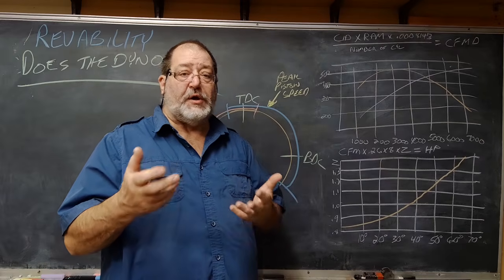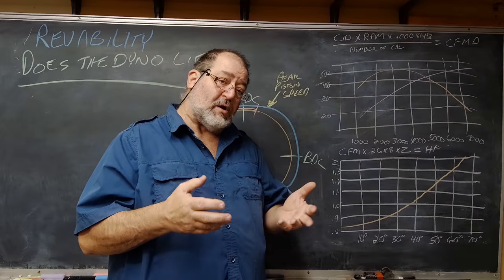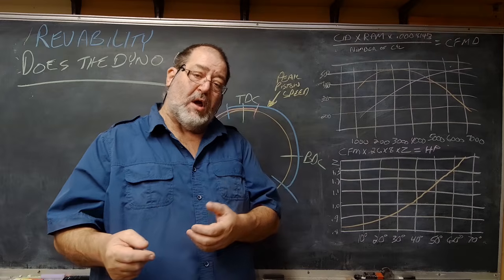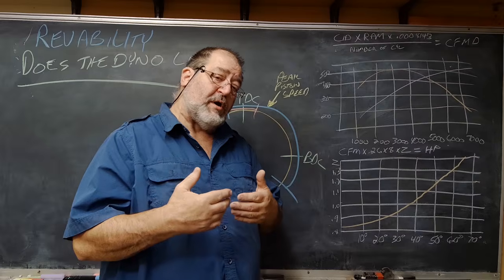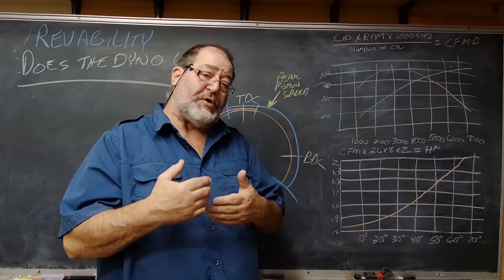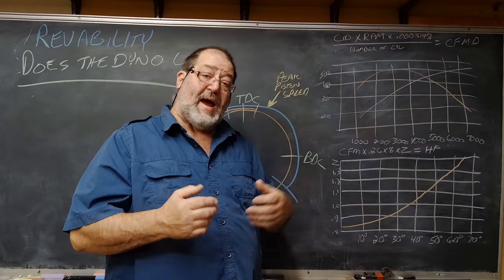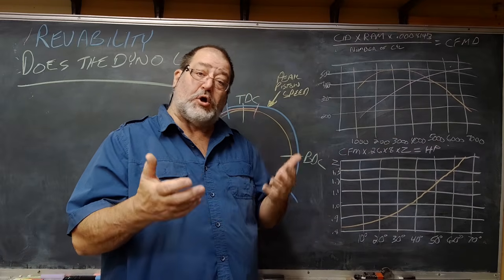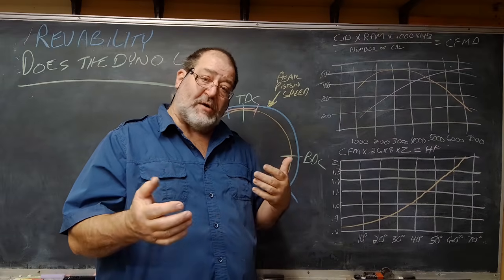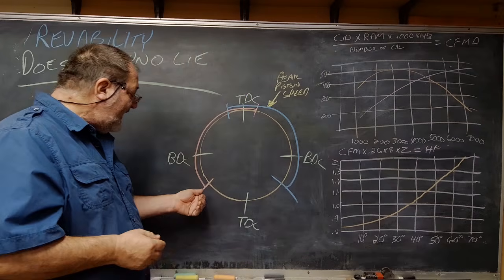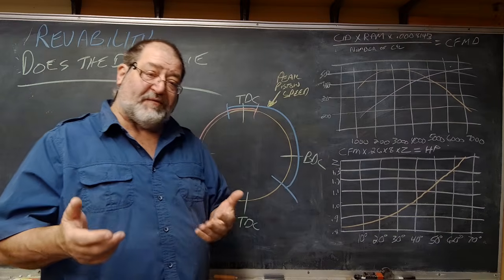Well, what you're going to do is not really make peak happen later, because you're flow limited, but you're going to make the carryover do way better: how much power you make past peak, how well you carry that same power up to a higher RPM. And this can show up as a better curve, and the engine will behave better and you have a wider power band. And a lot of that has to do with your blowdown point. And so you have to watch your events.